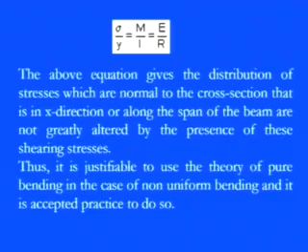That means sometimes when we know that non-uniform bending stresses are also there in those cross sections, we can still apply the normal stress concept: the normal stresses are there along those fibers, on top of the fibers we have tensile stresses, on the bottom compressive stresses, and we have a neutral axis.